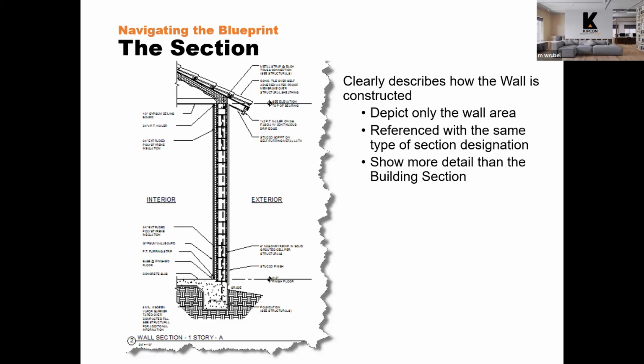Wall sections are very valuable when you are looking for information on how the building is constructed, when you do need to do remedial work. These sheets are very important to people who are designing siding or designing repairs for stucco, or if there are issues with water intrusion into a building. These wall sections are very important because of the amount of information they show, and because of the information they show in how what might be leaking relates to other portions of the building. So these sheets are very important to have if you have them.